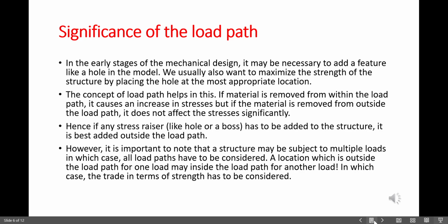And what is the significance of the load path? Now, if you see the engineering structures, we need to accommodate various stress raisers like holes, bosses, slots, etc. However, often we have a choice about where we can locate them. So, in order to decide where we can place the stress raisers, this concept of load path is important.